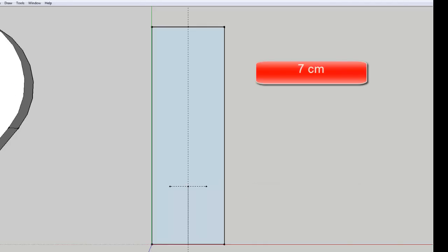using your tape measure tool, we want to make another mark at 7 centimeters. So go along the line, along the green axis, 7. Okay, that's a point at 7. And go further from that point, make another mark, going along at 2. All right. Now, here we go.